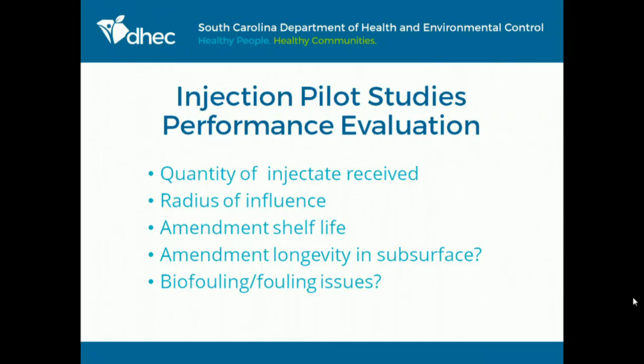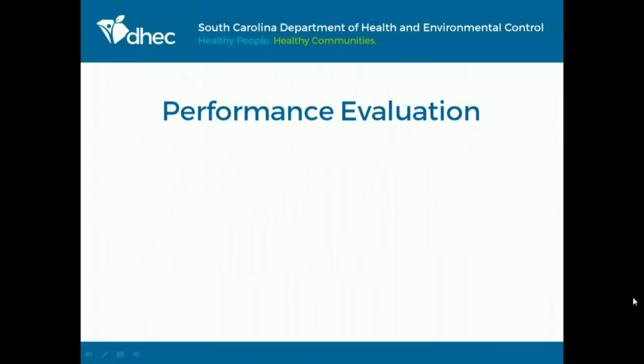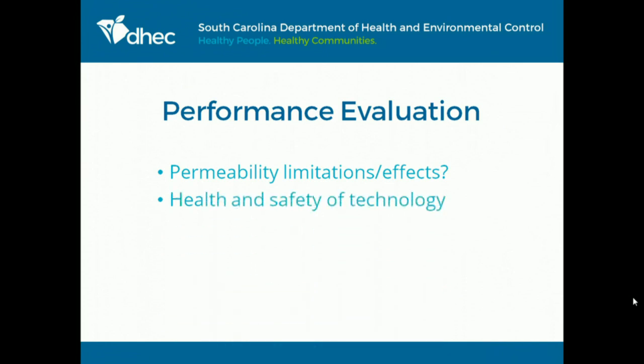Biofouling and fouling. I think that is one of the best reasons to do a pilot study. If there's a potential for biofouling or fouling, so much better to find it out up front. Are there permeability limitations and effects? Are you going to have trouble injecting because there's too much clay? It's good to find that out before you select that as your final remedy for a site.